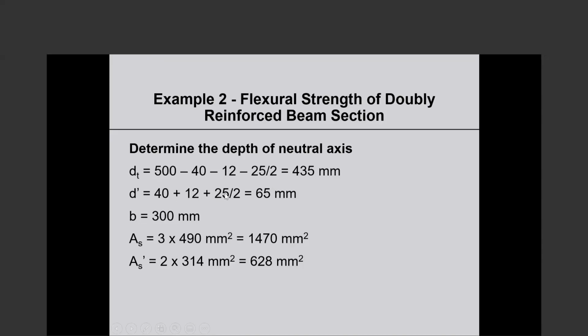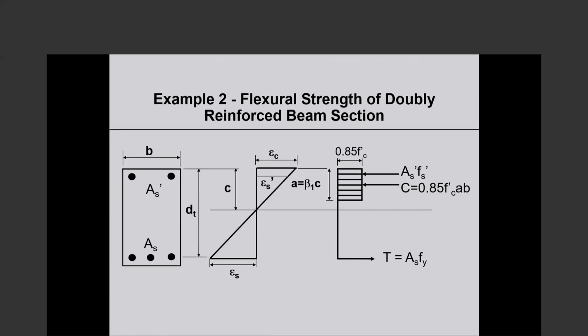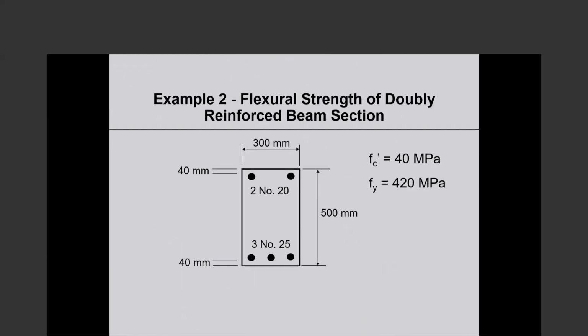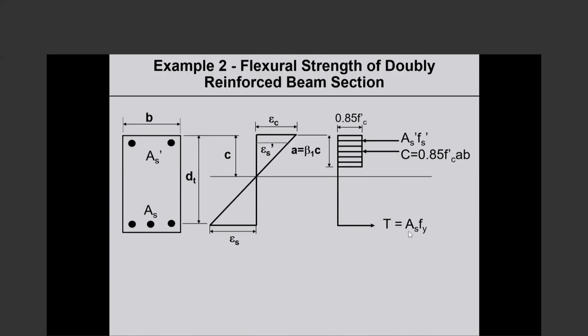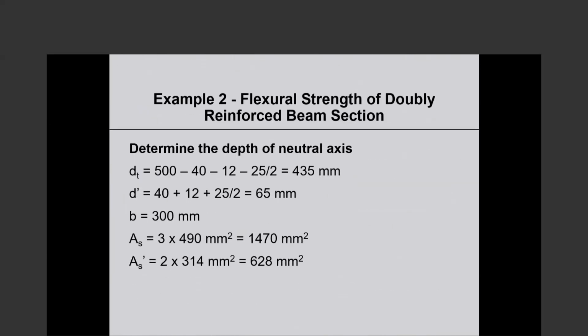The compression bar is 20 millimeters, so that should have been 20 by 2. So that would give us 52 plus 10, so 62 millimeters rather than 65. We will make that correction. Again, I see these things only while presenting, not before. We did say 20 millimeter bars. Okay, so that should have been 62. But listen, this is how it goes.